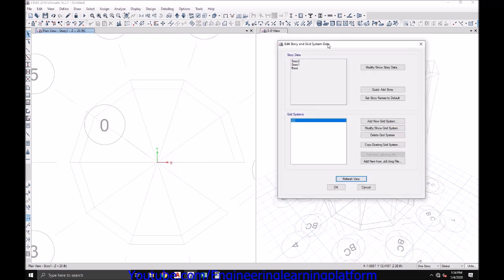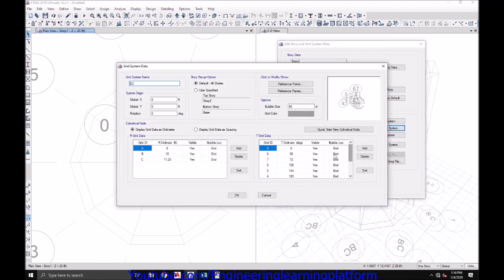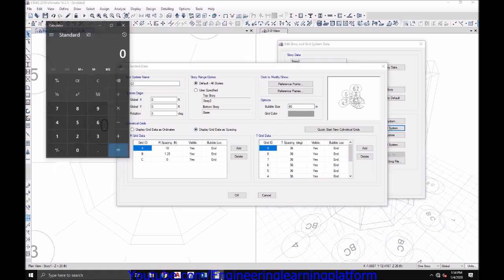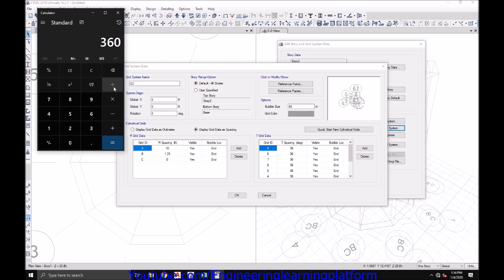Still I won't be getting 4 columns at equal spacing. So you might encounter these kind of problems when you have to space the columns. The finer the meshing or the grid, the slower will be the model.